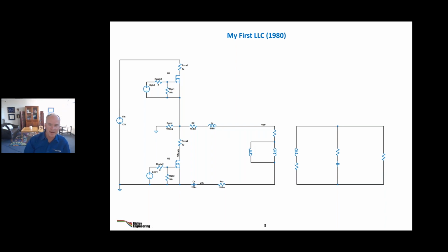Now, some of you may say, okay, well, that's a pretty simple circuit because you don't have the diodes and it's not non-linear. But to make up for that, the output voltage that I was dealing with was 6,000 volts AC. So that was a challenge, especially in the hands of an undergraduate student who had no idea about corona and breakdown and winding transformers. But I learned so much in those days. There's still aspects of that converter that I teach today. And so that was one complication. How do you wind a transformer with 6,000 volts on the output?